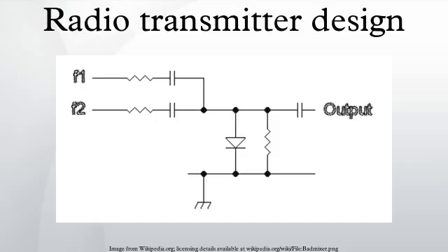High-level modulation uses Class C amplifiers in a broadcast AM transmitter, and only the final stage or final two stages are modulated, and all the earlier stages can be driven at a constant level. When modulation is applied to the plate of the final tube, a large audio amplifier is needed for the modulation stage, equal to 1/2 of the DC input power of the modulated stage.